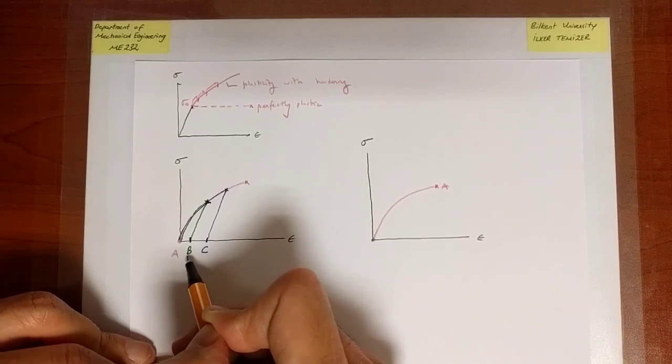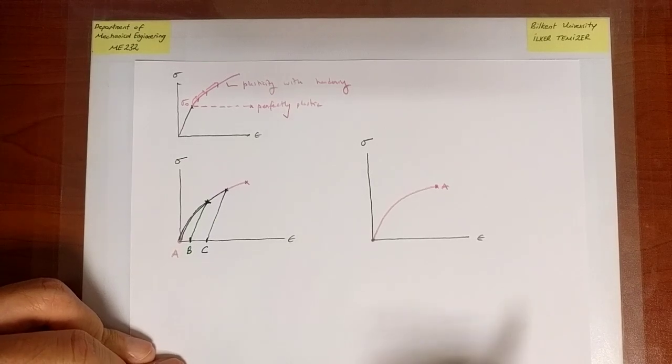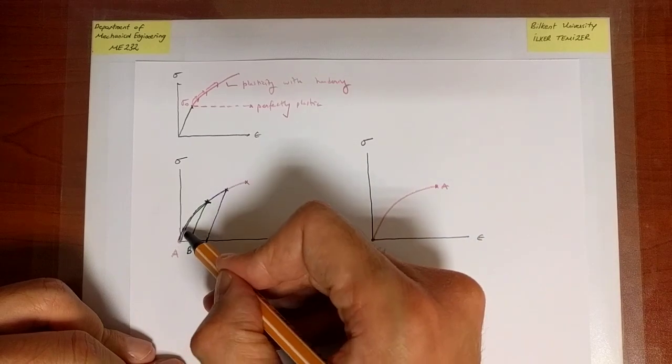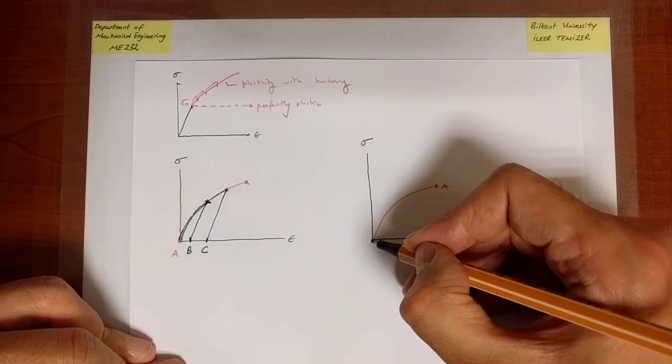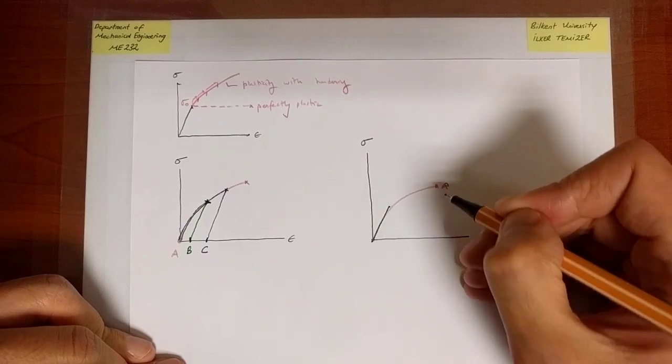Now I take that specimen and give it to another tester. That tester, this new person, has no idea that this specimen has been previously tested. And he puts it into the lab and he does a tensile test experiment. And what he will observe, first of all, is that it will have a slope in the elastic region that is similar to the original specimen.